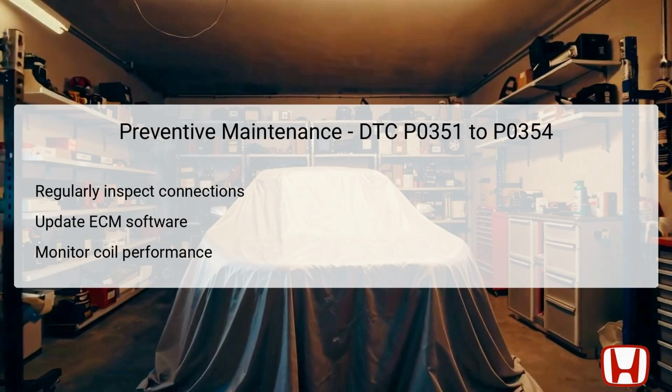It's also important to stay informed about any ECM software updates. Manufacturers often release updates that correct known issues or improve performance standards. Keeping the ECM updated ensures all control strategies are functioning as intended, minimizing the chances of DTC activations.